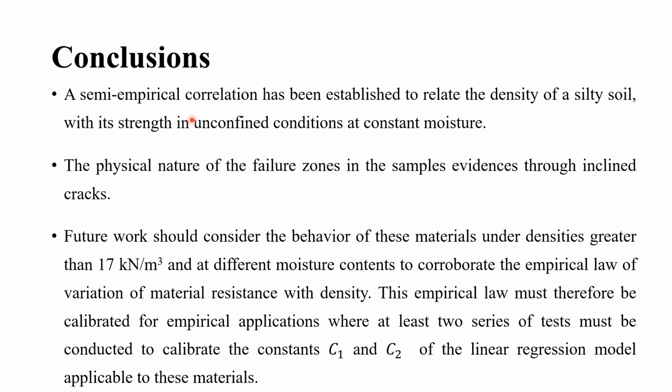Another very interesting result is that the physical nature of the soil failures was very similar in the soil samples, which is one of the main features of the soils, which tells us with the background of the soil mechanics theory that the soil is going to behave in a very similar way, which means that the friction angle and the cohesion are very similar, and it only depends on the nature of the soil particles and how they shear each other.